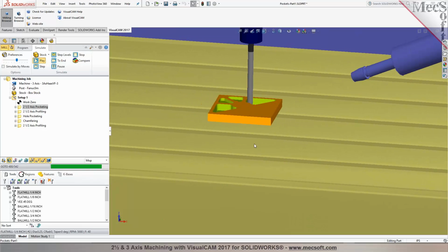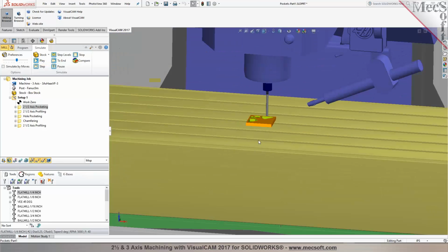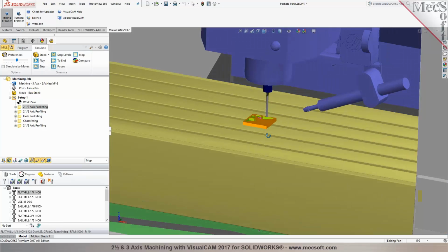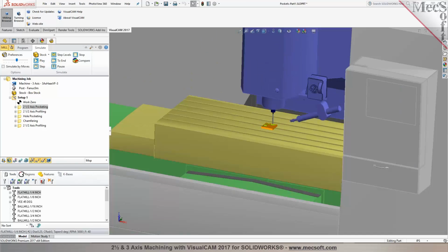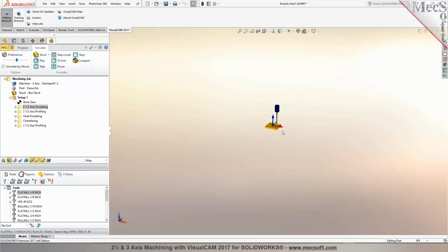In that point, what kind of machine options, accessories can be added here? For example, vices or other part holders can be defined, or besides the stock part, is this only concentrated on parts on the machine view? This is basically just to show the material removal simulation. So if you need to display the vices, you would actually have to build it as an additional part in SolidWorks maybe. Yep. So it's primarily used just for verification purposes in here. Okay.